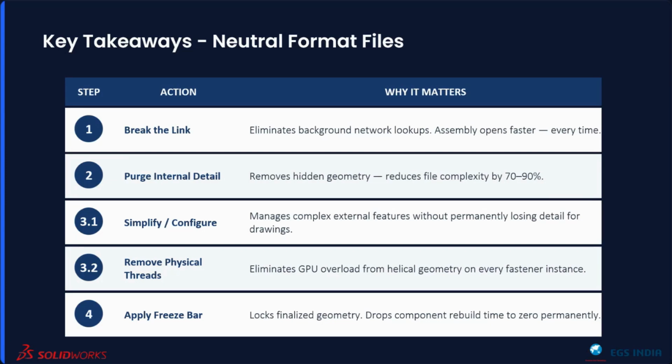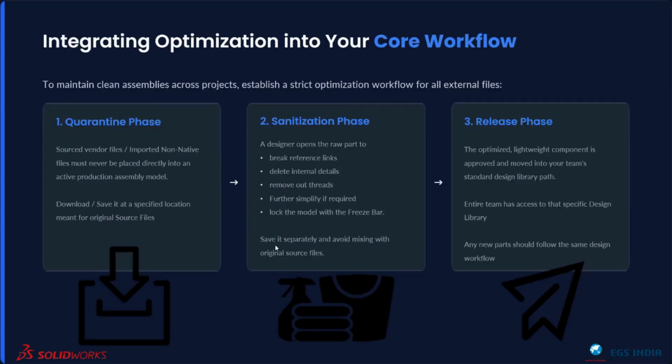So this is where we have something called a workflow that I'm just presenting to you now. The first is going to be the quarantine phase. What we recommend is first dedicate a person or a team who's allowed to download and add your standard component step files, etc., into your design workflow. So not everybody gets access to download the files.